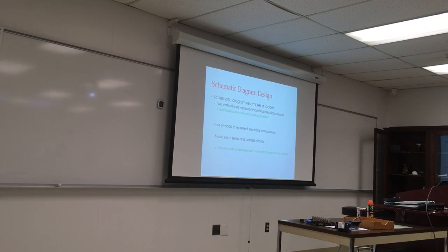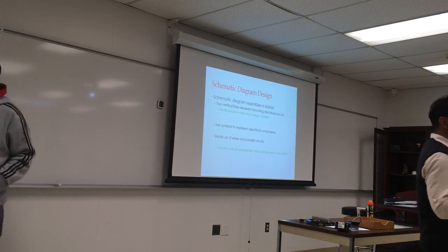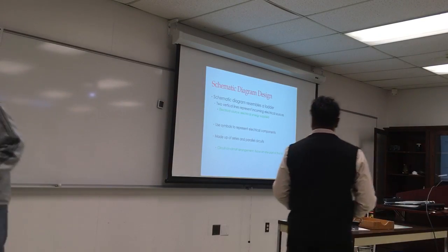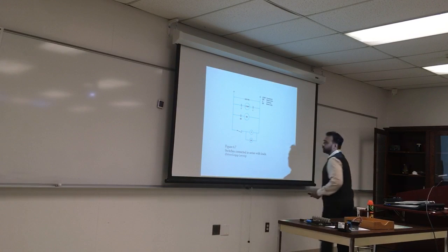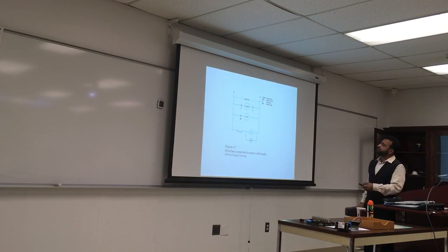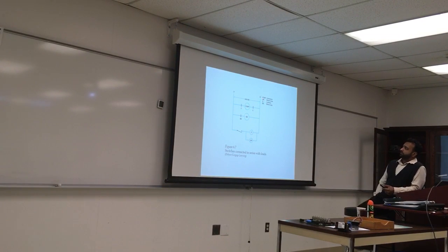And now you're getting exposed to a lot of components. You have the book with you, so you can become more familiar with it. What about this one here? Very easy. Compressor, blower motor, contactors, blower relay. What is the line voltage here? 240.